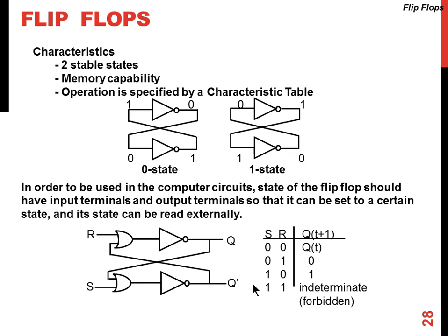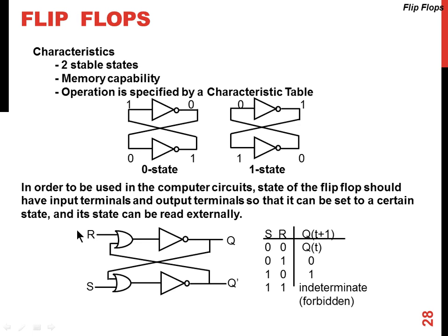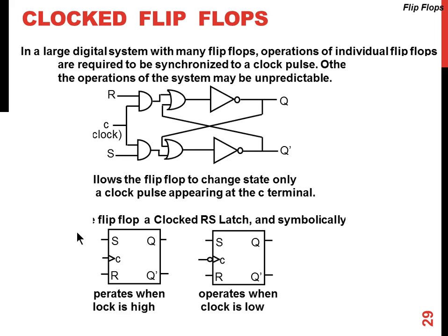So these are normal flip flops, SR flip flops. This is a clocked flip flop, where there is a clock involved for the flip flop. And then we also have basic latches and flip flops. The latches that we work with typically are level sensitive devices, which work at the logic high or low level. Flip flops are typically triggered by clock edges. That's a typical difference between latches and flip flops.